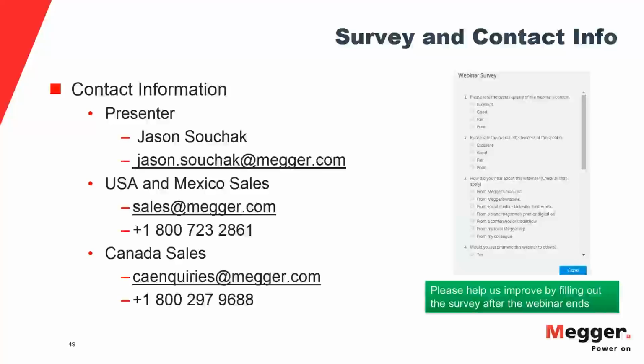There's nothing you can do about background noise. You just have to measure it and live with it. And if you're in too noisy of an area, you may not be able to do effective testing. But like I said, in my experience, background noise can be as low as maybe 20 picocoulombs, about the lowest I've ever seen, up to about 150, which is about the threshold where we can do meaningful testing.